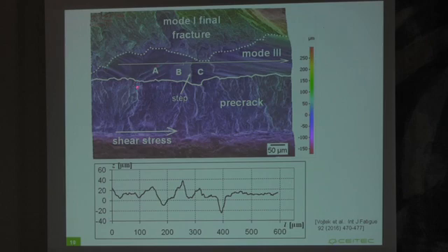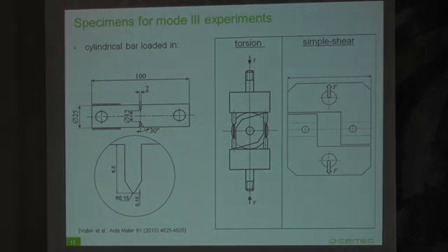For example, in this case, the crack initiated and grew in segment A in this direction, and then continued into segment B, which is another grain with a differently oriented slip system. In this segment B, the crack grew upwards in the third dimension. Meanwhile, in another place, the crack grew in segment C in this direction, and then they met at different heights. So they need to be connected by creating such a step observed here. So it confirms the model of local mode 2 crack growth mechanism.